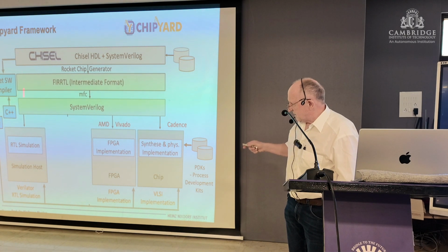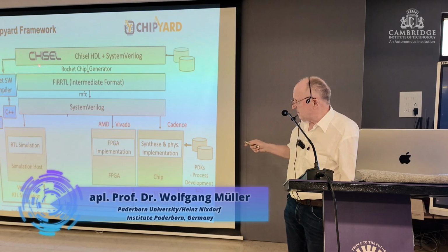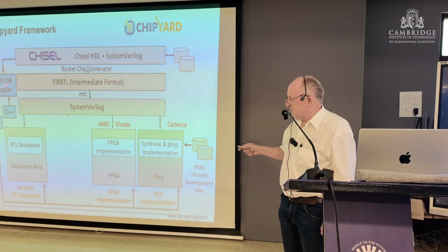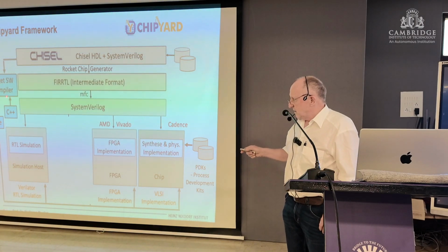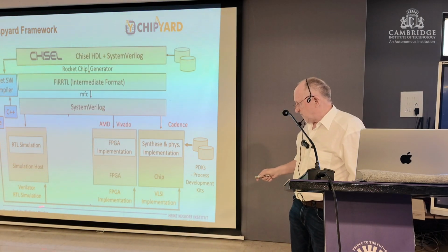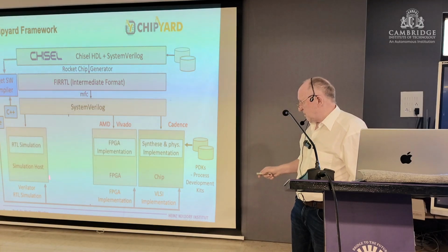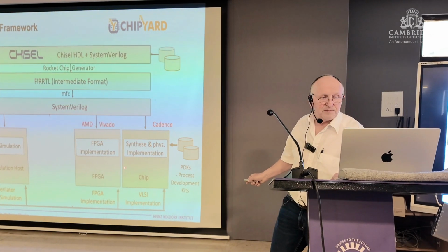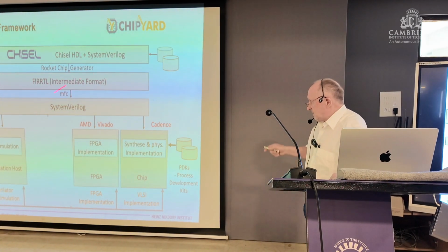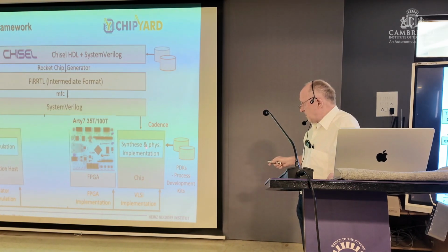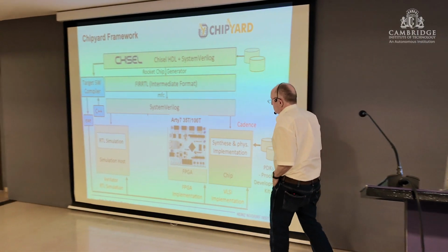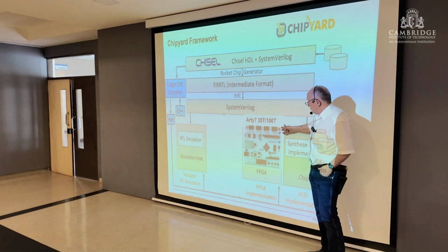And here, as the other path from Chisel, you can automatically create a so-called target compiler, which gives you the exec file you can then load into the RTL simulation and also FPGAs on the chip. So this is our basic framework. At the university, we are using low-cost FPGA boards.